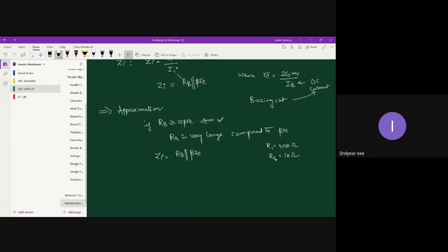These are very helpful in your competitive exams, wherein you will have to find the range. When these two are connected in parallel, your equivalent resistance will be very close to the least resistance among the lot. That is 1 kilo, so it is slightly less than 1 kilo.